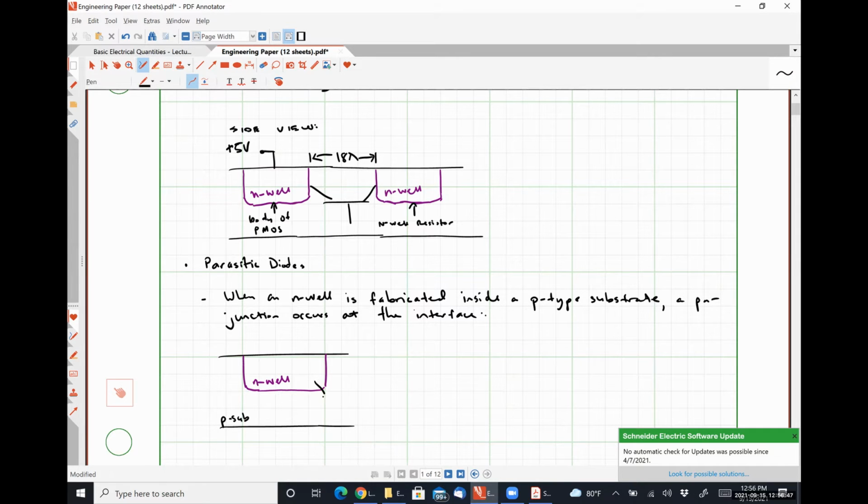And the N-well region effectively acts as the negative polarity terminal. I say that because I can't remember whether cathode or anode is the one with all the electrons. I always get it backwards. And our substrate acts as the positive polarity terminal of a potential parasitic. Oh, I wrote it down. I'll be damned. So N-well is a cathode, and a P-sub acts as the anode.